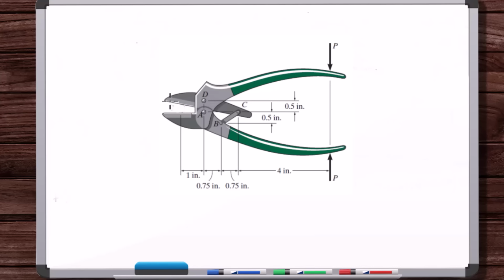Okay, well now here, if we look at all the exposed surfaces, here's two exposed surfaces, but we know there's forces on them. So we're assuming there's no friction, let's say, so it's a smooth contact. So a force normal to that blade and a force normal to that blade. And we put the direction because we should know the angle of this blade, so we know the angle of this force. So now, without the twig, this is the free body diagram, these two forces and these two forces.